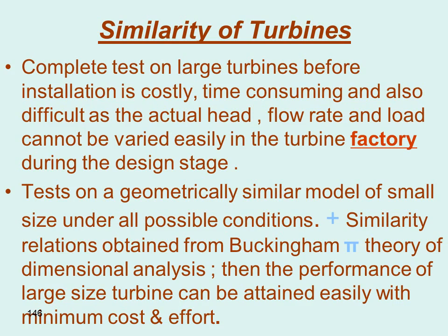Tests on geometrically similar models of small size under all possible conditions, the results of these tests, plus similarity relations obtained by the Buckingham theorem of dimensional analysis, mean the performance of the large size turbine can be attained easily with minimum cost and effort.